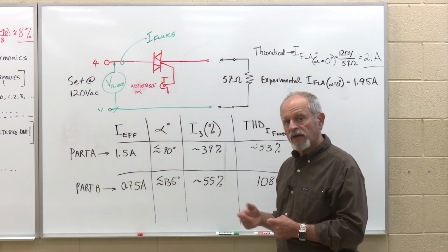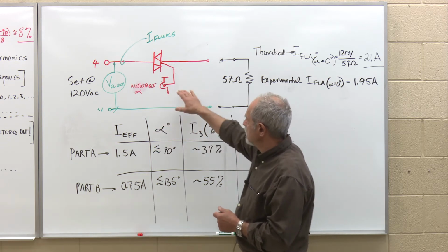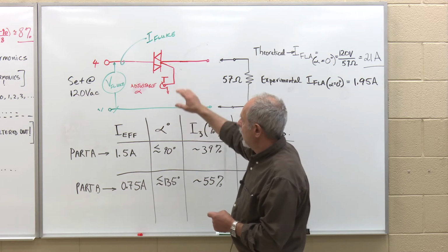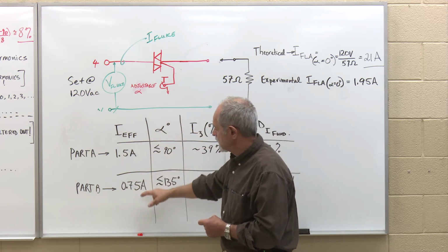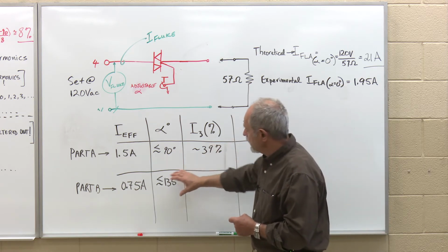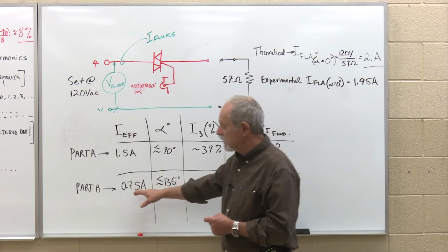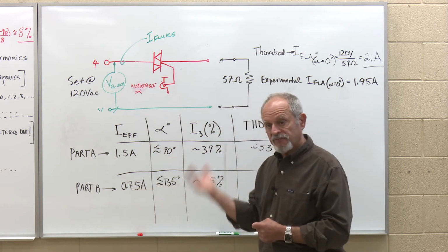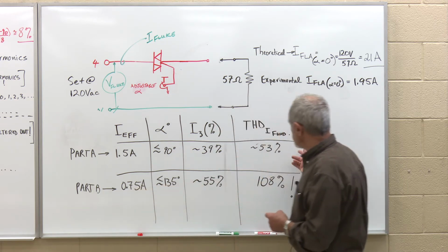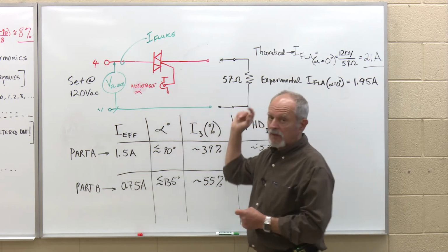And the reason for that is because as we keep adjusting this angle, we are essentially increasing the contribution of all the harmonics to the reduced current. So in effect, the current becomes more and more distorted as we approach an angle of 180 degrees.